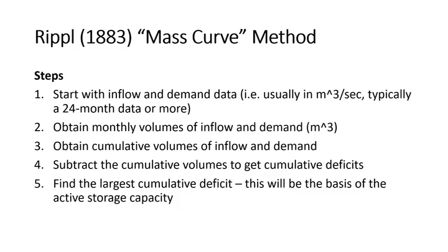By cumulative, we just add the sum from the previous months and all the preceding months. And then from there, we subtract the cumulative volumes to get the cumulative deficits. Basically, we subtract the cumulative demand from the cumulative inflow.